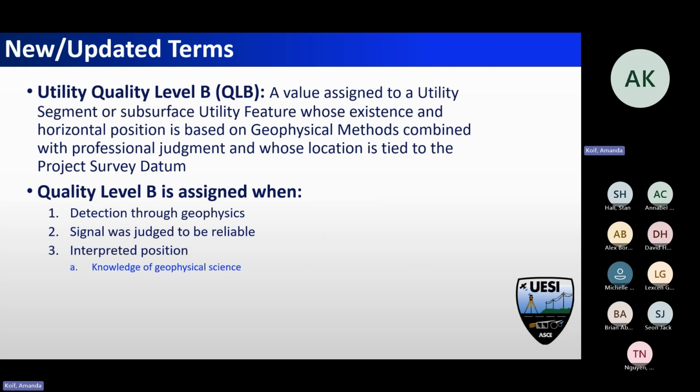I set up my pipe and cable locator. Is it in the correct position? Am I on the right frequency that I should be using to mark that certain kind of line? You can ask these questions if they're not finding things in the field, and that way you have a better understanding of what kind of data they're finding and giving back to you, because you're the one that's ultimately going to sign and validate that data.